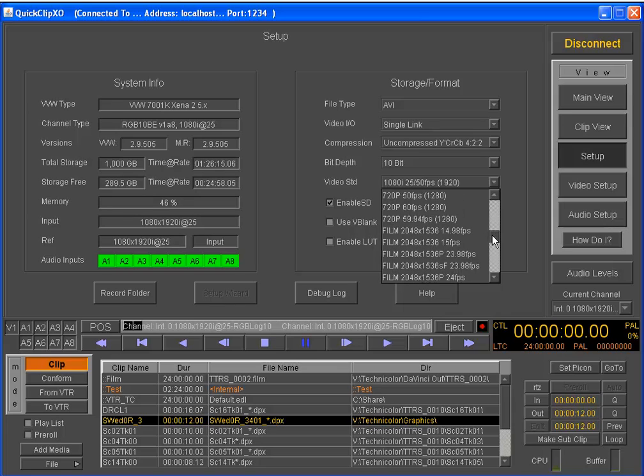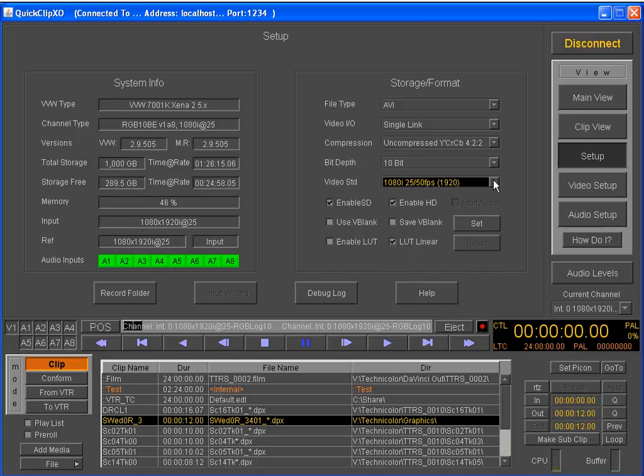The Drastic DDRs support a wide range of video standards including standard definition, 720p high definition, 1080i, P and SF high definition, and 2048 digital cinema standards. Depending on your particular DDR, HD-SDI 2K film transfer and real-time 2K playback with center cut HD may also be supported. If you are running the DDR as a DVI playout device, you can also play back at VESA, 1K, 2K, 4K, as well as custom resolutions and frame rates.